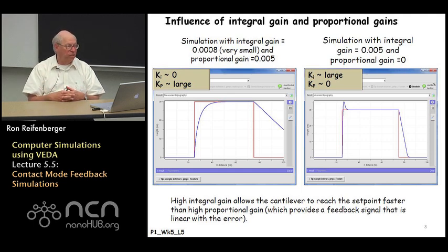And what you can see very clearly is that the substrate motion with respect to the tip misses pretty severely on both the leading and trailing edge of the feature. So from your AFM image, you might conclude this feature really has a rounded leading edge and a long sloping edge, if you just blindly believe the image that the AFM produces.